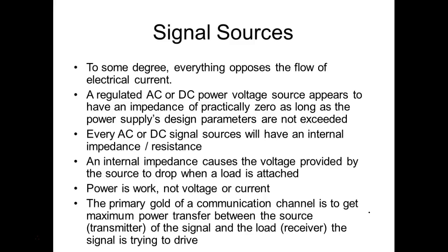Signal sources don't have that. So as soon as I load a source of a signal down, it's going to drop. You understand that? We don't regulate signals. We don't regulate power. And this is what happens. This is why when we have shorts on a regulated power supply, it flat will burn stuff up because it keeps pumping more energy in as long as it can, right? You understand?